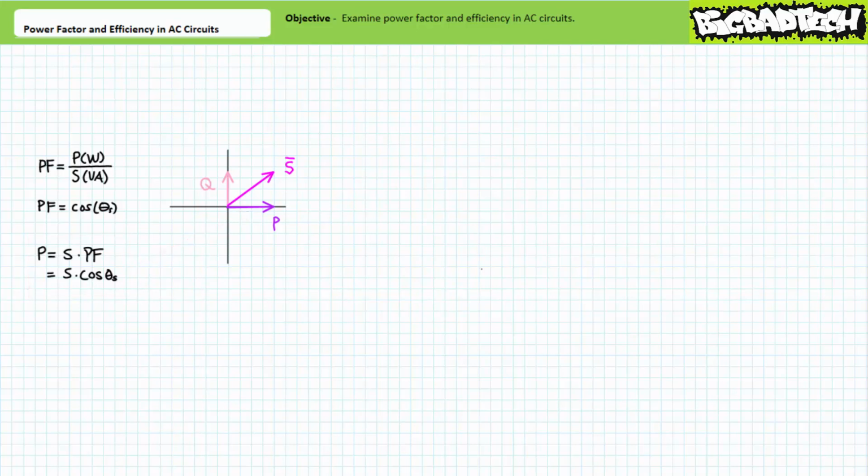Real power is that amount of power that can actually be put to work, either heating, lifting, lowering, grinding, crushing, or moving something. What might not be obvious is that by extracting the real dimension from apparent power, power factor essentially strips apparent power of the reactive power dimension. Reactive power, measured in units of VARs, is that amount of power cyclically absorbed and returned or exchanged with the source. Reactive power, while an important property for magnetic loads like motors and transformers, doesn't actually get put to work.